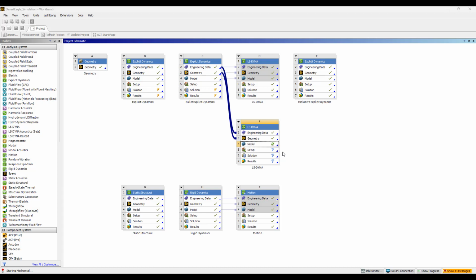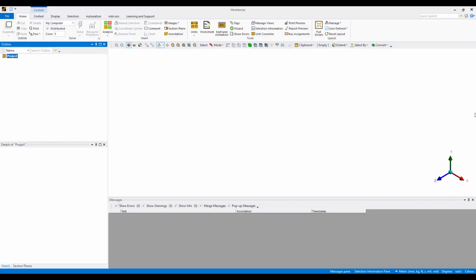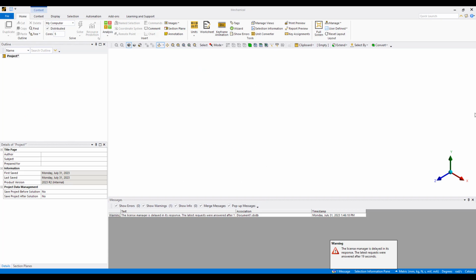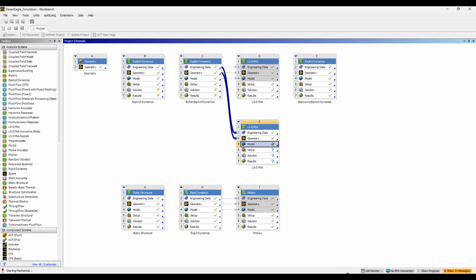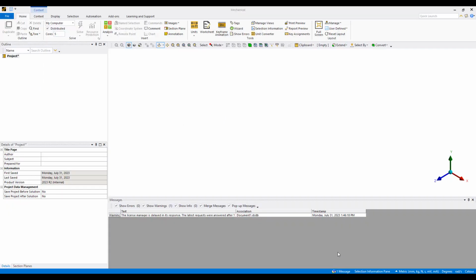There is the ability to create a body interaction that automatically handles all of the contacts and connections in an assembly. However, this also leads to some unique challenges because unexpected or unforeseen contacts can occur depending on the size and quality of the mesh. So sometimes that is necessary to take into account.